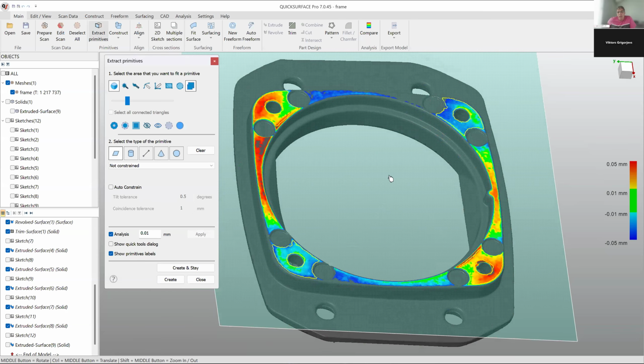Now, what you see here is actually a very good tool to show the imperfection of the manufacturing, how the machine has been working. You see a tendency that one side is in blue, the other one is in red. So this means that this plane has actually been deformed somehow for one reason or another. So I hope this answers your question.